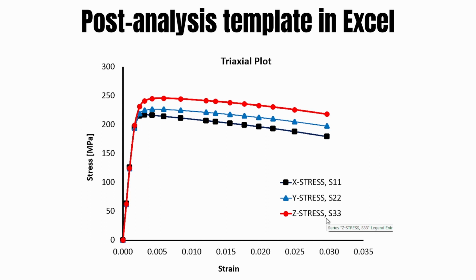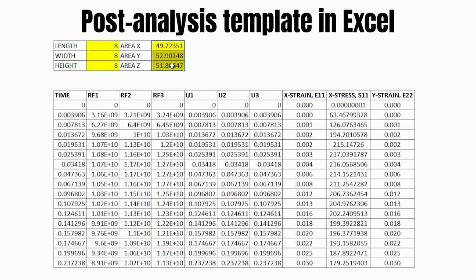And this is really interesting because when you think about what's happening here, why are they all different? After all, it's the same load that is applied. But the clue you can already see from above. The first thing is that the areas of the surfaces are actually different because of the effect of the voids. That suggests a different stress history. Also, internally within the system, the distribution of the voids in some cases may be intense, and in some cases it may not be. And so you tend to have different stress forces and reactions in the system, and that's what we see here.